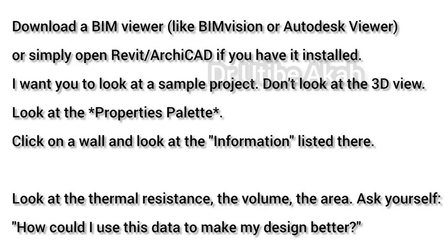Your assignment for this week. I want you to download a BIM viewer like BIM Vision or Autodesk Viewer, or simply open Revit or ArchiCAD if you have it installed. I want you to look at a sample project. Don't look at the 3D view, look at the Properties palette. Click on a wall and look at the information listed there. Look at the thermal resistance, the volume, the area. Ask yourself, how could I use this data to make my design better?